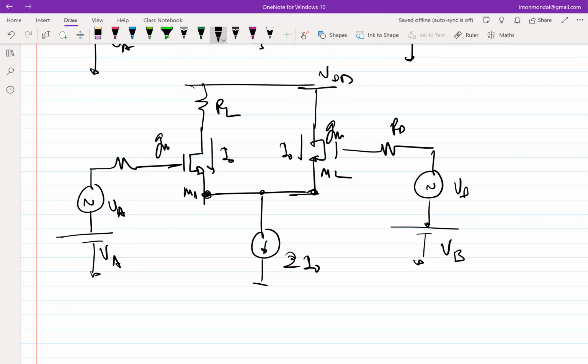I'm sure you all have seen it in your UG textbooks multiple times. But the essential genesis of this differential amplifier is that of a common source amplifier whose source cannot be loaded with another terminal, right? So essentially, this is like a common source amplifier whose source is driven by a common drain amplifier. And it is not a surprise that the transfer function of this is similar to that of a common source amplifier, right?